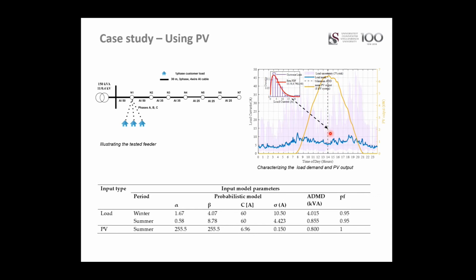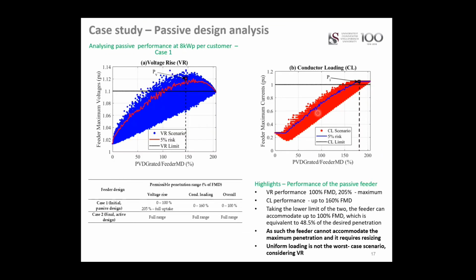where we expect that there would be low loads, and at the same time there is higher PV generation. So in that case, if we are modeling this, I think from the background and the way you've explained, we expect that the voltage will be high at this point, since there's a lot of injection going into the network. So I don't know if that also explains something.